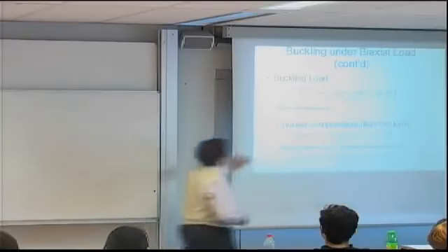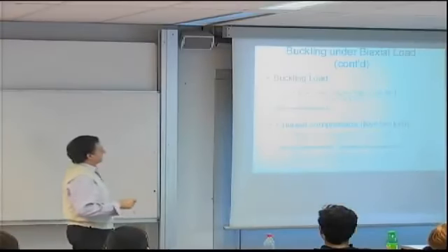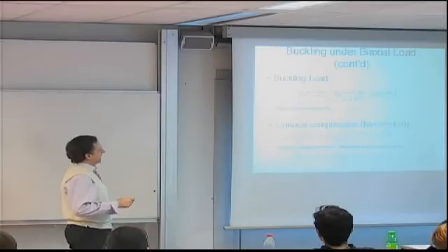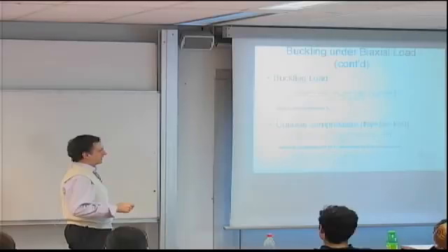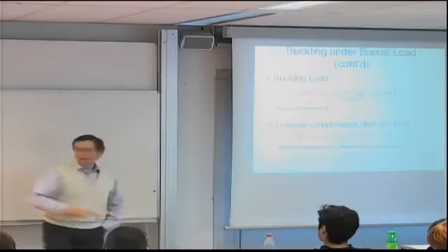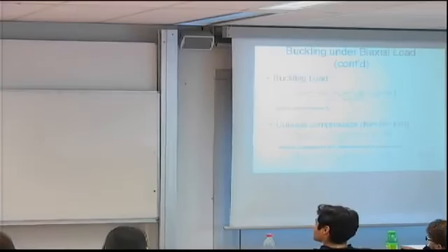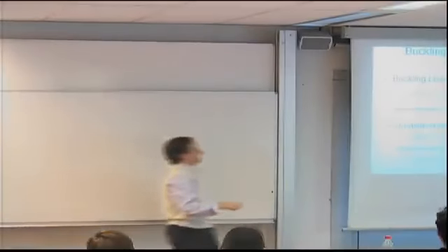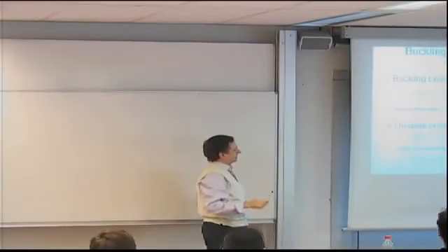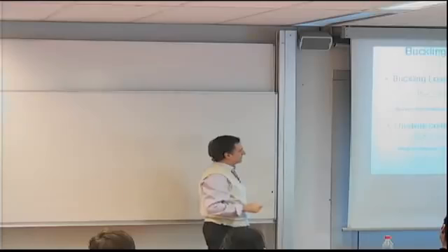And we arrived at the buckling load by equating all these terms. And for the special case of uniaxial compression now, that means Ny is 0. This load here is 0. So K would be 0. If I set K to 0 in its denominator, I arrive at this quantity.